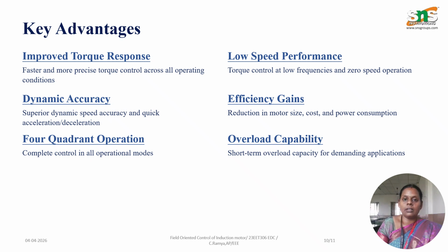Next, we come to the advantages. FOC offers several advantages. It provides fast and precise torque response. It performs well even at low speed and zero speed. It ensures high dynamic accuracy and efficient operation. It supports four-quadrant operation and handles overload conditions. Overall, it improves the motor performance, and efficiency is also significantly improved.